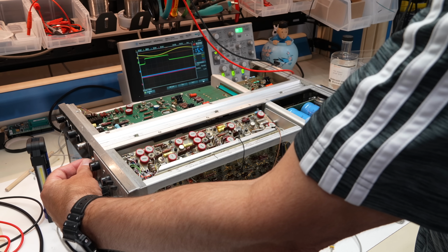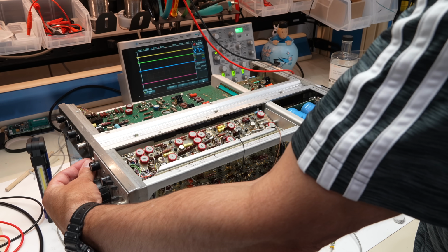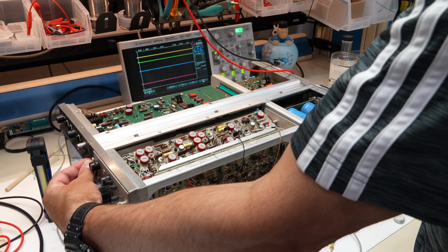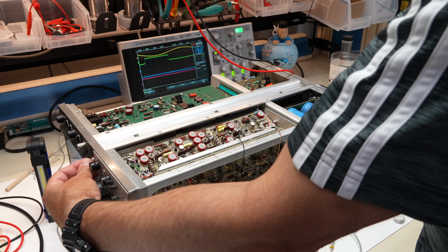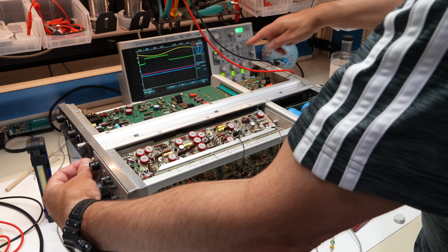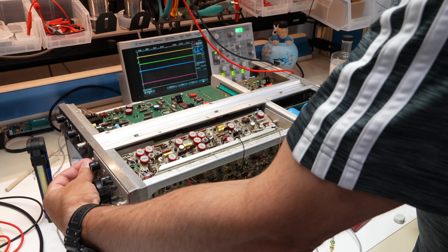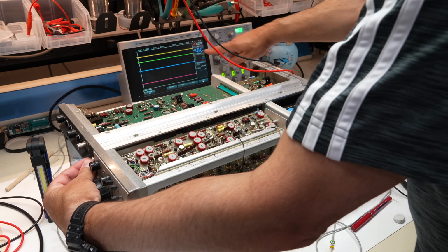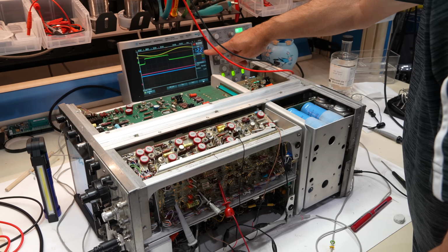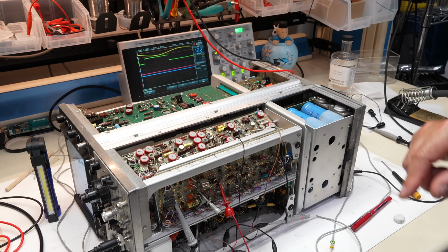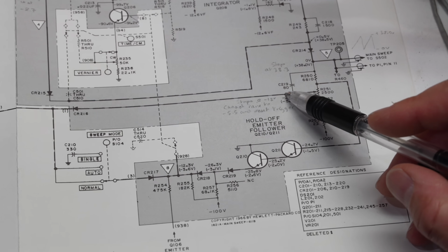And they wait. It started good and something not good happened. So they move together. And that stops at minus 12 volts. That is not correct. I have it here actually, by pure luck. Yeah, it stops at minus 12 volts. Yeah, it should stop at minus 5.5. I bet you that's our problem.